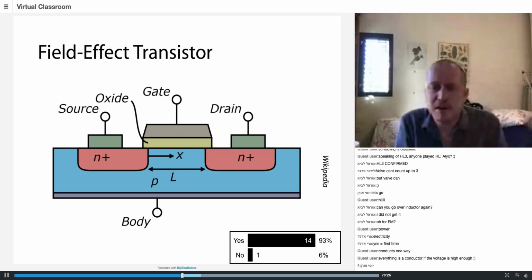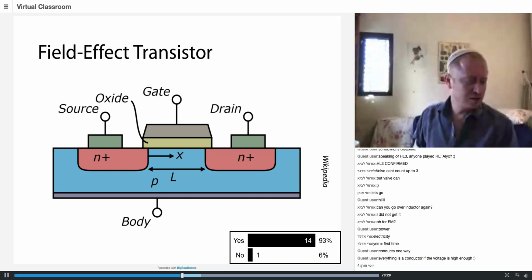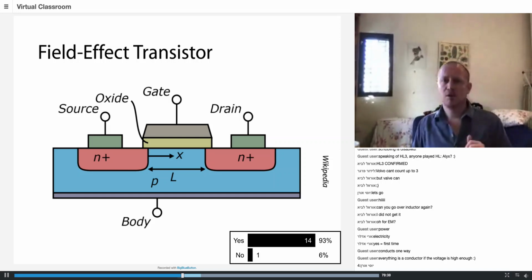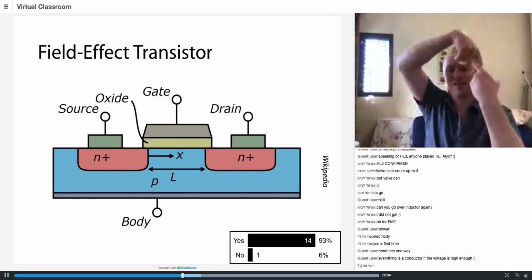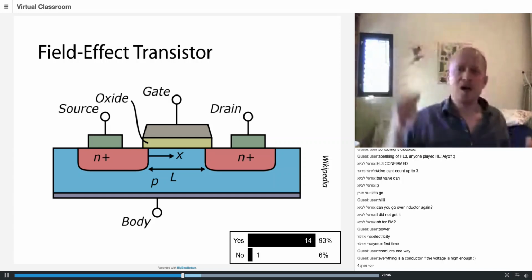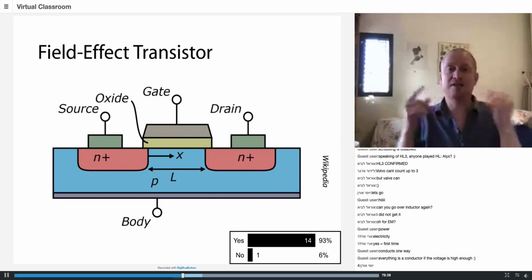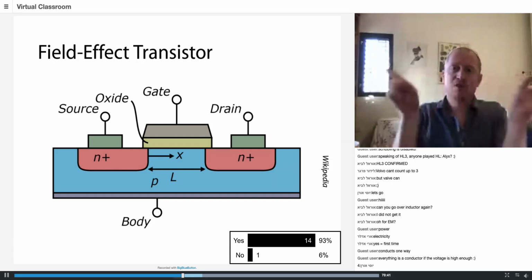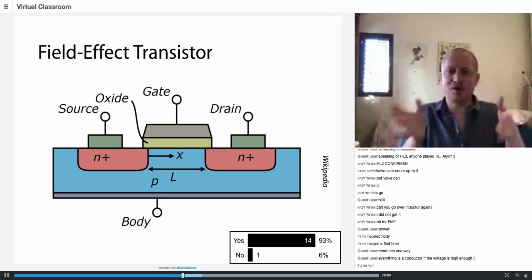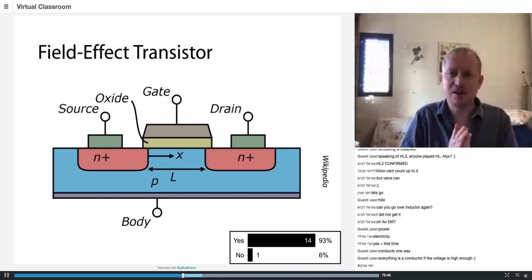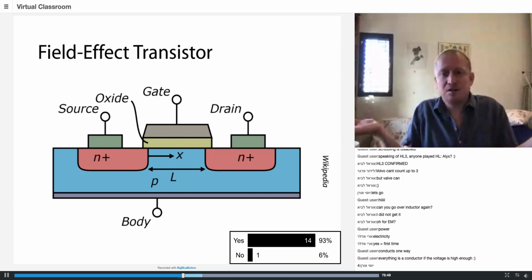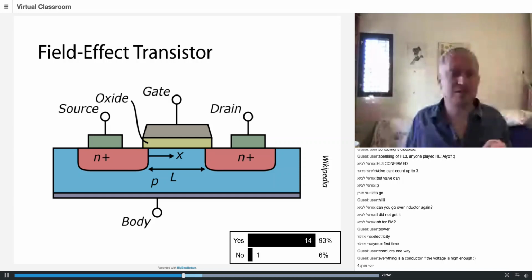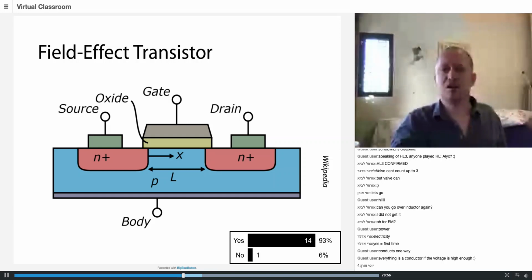But if you have, for example, silicon which is doped with boron, all of the silicons create this beautiful valence bond, but the boron material only has 3 electrons. So 3 of the directions of the boron are connected wonderfully to the silicon. And in one of the directions, there is nothing connected on the other side. And what this nothing is called in Hebrew is called choronim.